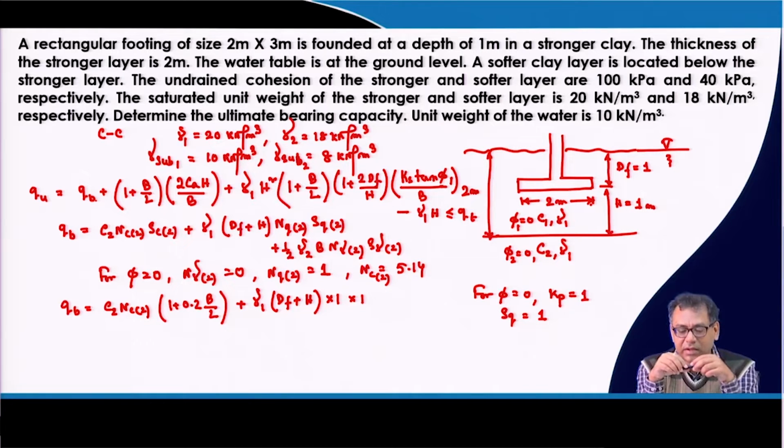But for an inclined footing you can put those recommendations which are given in the original bearing capacity equation by Meyerhof. So, that is why when I calculate qb, we take the shape factor originally proposed by Meyerhof, given in the table. So, remember that